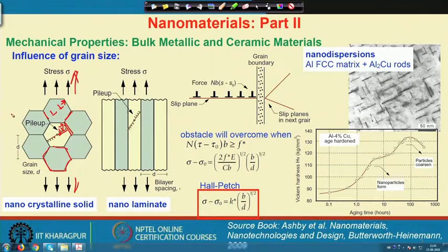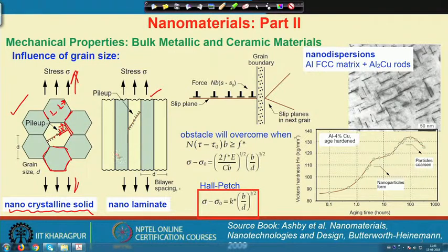So, this is, let us say, the case of an equiaxed structure. However, the size scale could be in the nano range, where we bring down the scale, we can dream about such a situation, or we can think about a laminated structure, where inside the laminate a similar situation arises: dislocations will try to flow and they will pile up at the interface.